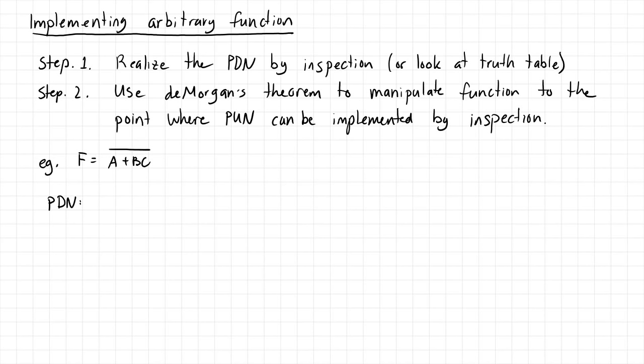So we know an OR construct is 2 parallel transistors. The current can go through one path or the other. It doesn't really matter which one or both. Both will achieve the same function. Similarly, the AND construct is 2 series transistors. So if we want B and C, then we should put 2 transistors in series.